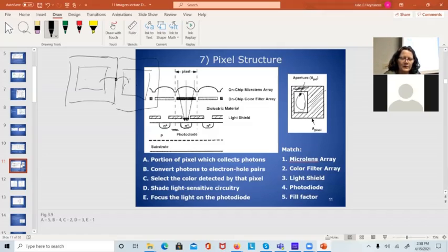And this is one way of fudging the fill factor: I put a little micro lens right next to the array, which has to be done right on top of the CMOS processing in the same silicon substrate. I put this little lens in there that focuses all the light that would have normally come down here back towards the pixel. So these are called micro lenses. And this is one of Guan Yang's ideas. He was probably the original guy who came up with this.